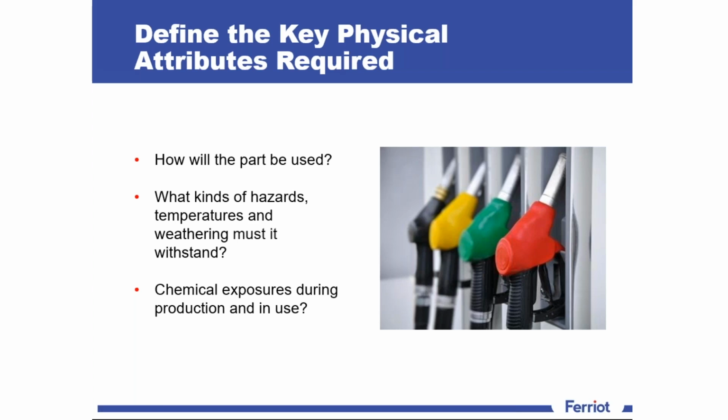Knowing the environment in which the finished part will be used simplifies choosing a resin designed to withstand potential damaging substances like automotive fluids, cleaning solvents, cutting oils, degreasers, lubricants, mold releases, paints, adhesives, printing dyes, and cooking greases. Outline the types of chemicals to which the part will be exposed during manufacturing assembly and its intended environment, and make sure the resin you choose is compatible with or can at least withstand these chemicals.